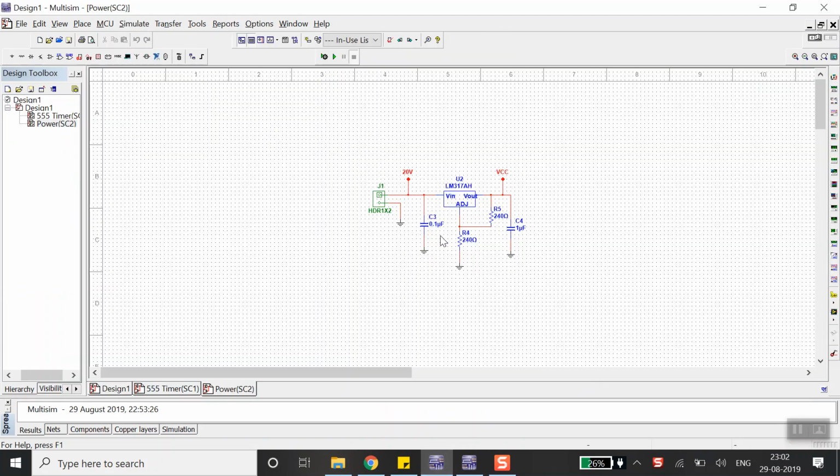So in this tutorial, we will add some components over here. Let's say that in the Vout I have to add one more capacitor, which I left out by mistake, or I thought I would just add it later. So let's just say Control C, Control V. I have added this component over here, and I'm making this connection. I have added one component, which is C5. One point is connected to ground and another point is connected to VCC, and it is supposed to be near C4.